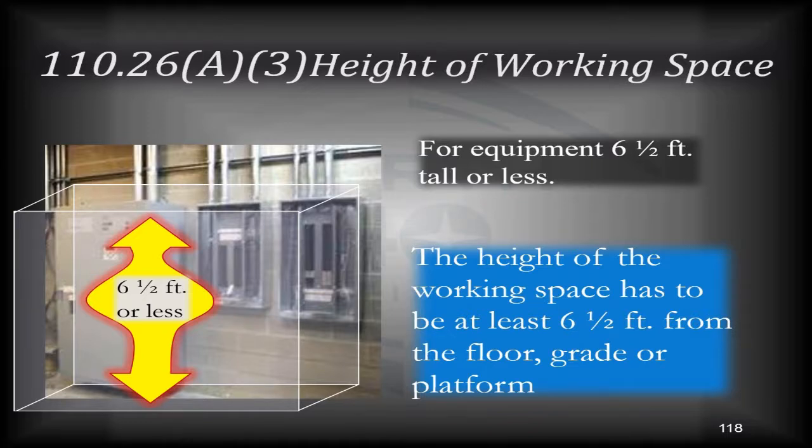110.26(A)(3), the height of the working space. For equipment 6.5 feet tall or less, the height has to be 6.5 feet from the floor, grade, or the platform, minimum.